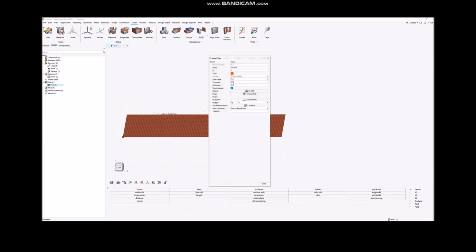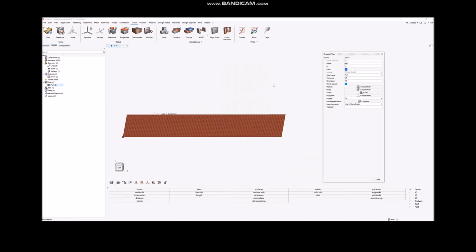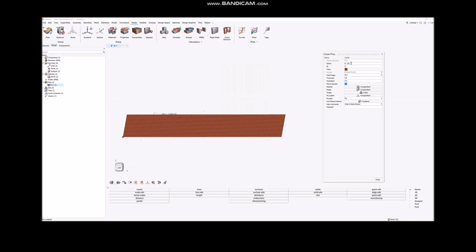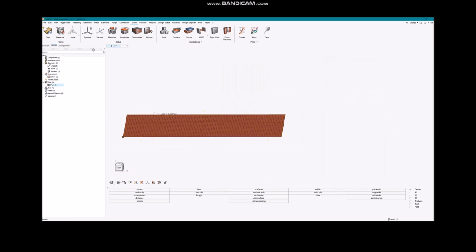As you can see, I define 3 plies: one at 45 degrees, one at 0, the unidirectional, and one at minus 45 degrees. Then I define the core, but we are going to use the symmetry of this layup, so the core is half as thick as it needs to be, so that after applying a symmetry to the laminate itself, it has the right thickness.